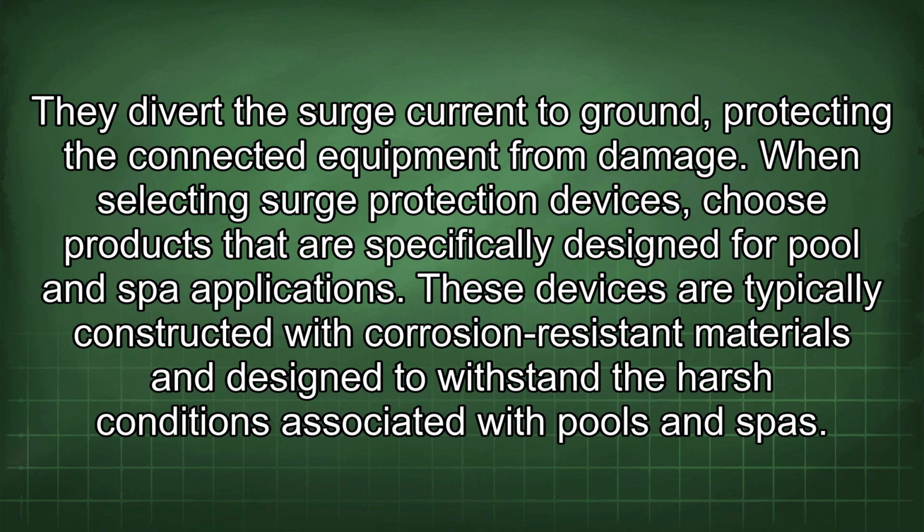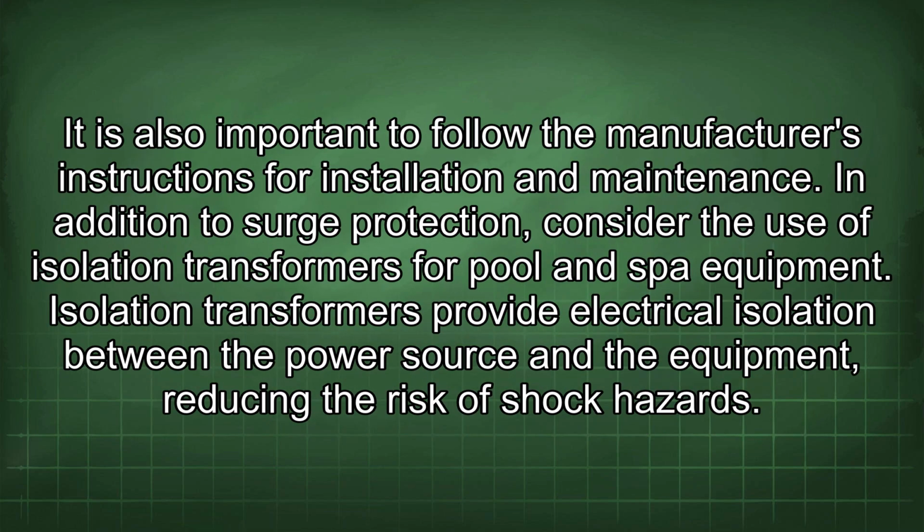When selecting surge protection devices, choose products that are specifically designed for pool and spa applications. These devices are typically constructed with corrosion-resistant materials and designed to withstand the harsh conditions associated with pools and spas. It is also important to follow the manufacturer's instructions for installation and maintenance.